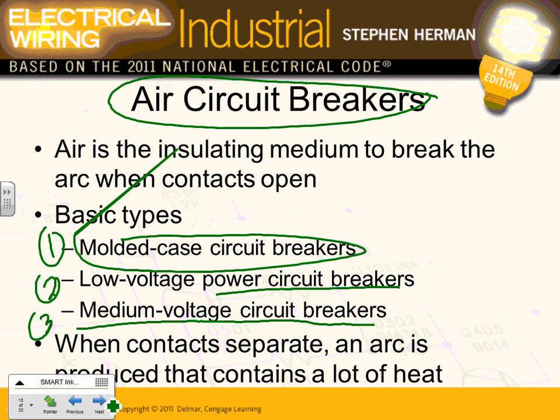Low voltage circuit breaker. Do you guys remember when Square D came here? And when you went to EMI, did you see big circuit breakers sitting there? They're big devices, a foot by a foot by a foot. They're not molded. You can look at the contacts, they draw them in. That's called power circuit breakers. Some of them are low voltage, some of them are medium voltage. 600 volt here, and this would be probably 5K, 15K, 25K. These are the medium voltage, or 35K, something like this.